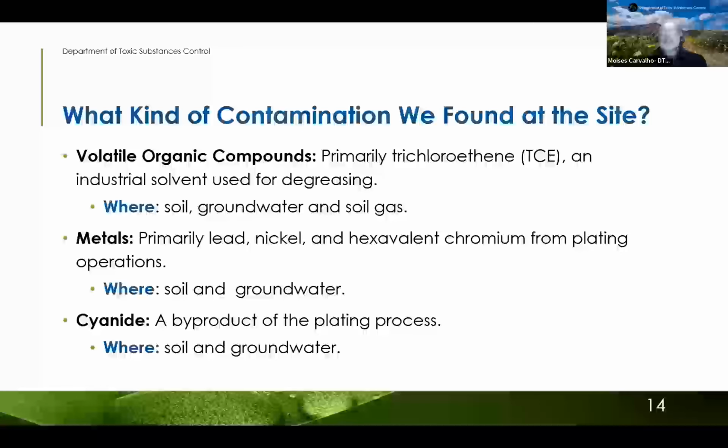In addition to VOCs, we also found heavy metals like lead, nickel, and hexavalent chromium, all of which are common in the metal plating industry. We also detected cyanide, which is a byproduct of the metal plating process. These chemicals were released into the soil and groundwater over many decades when the facility was in operation. Next.